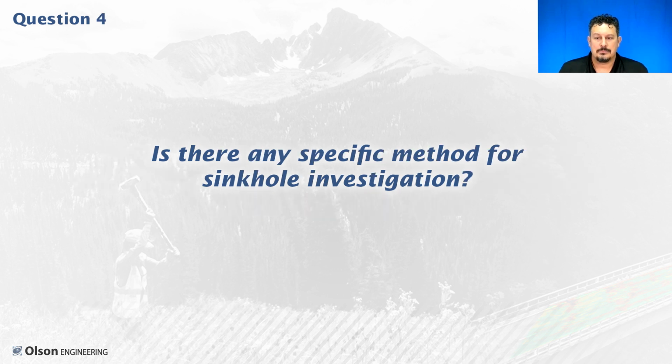Okay. Is there any specific method for sinkhole investigation? I guess the question is what do you mean for sinkhole investigation, right? So the first question is, are we just trying to define the extent of the sinkhole and the depth of it? Or are we trying to then look for the source? I mean, those are not the same thing, but they can be connected. So the first question is usually just defining the extent of it. And that can be done typically with different surveying methods, photogrammetry or ground-based robotic total stations or GPS.